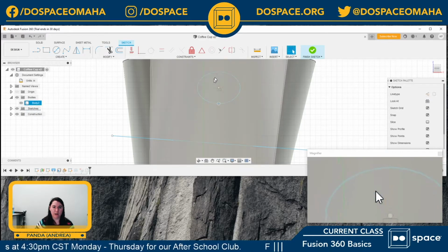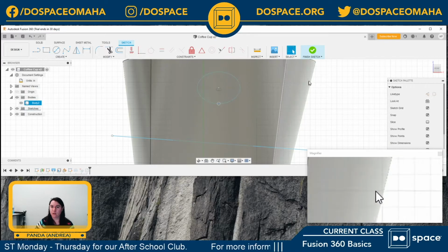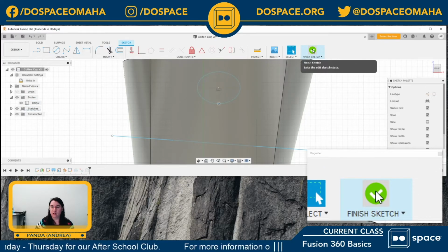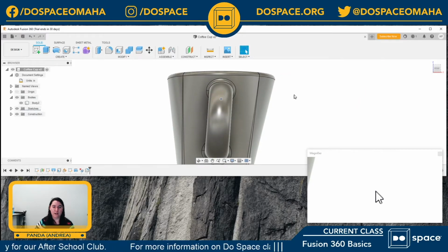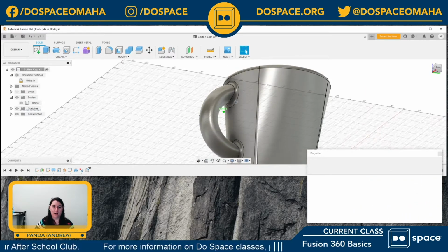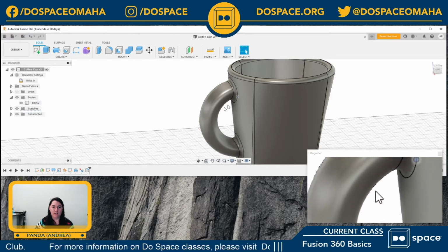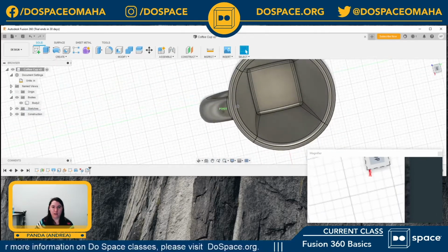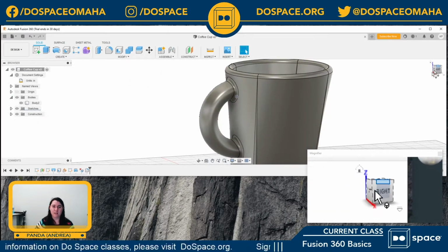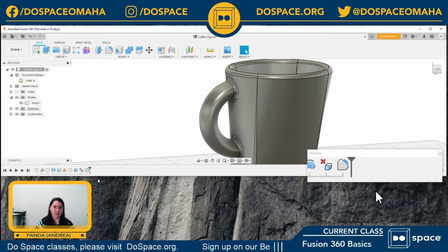So I'll change that right now here. I think that looks pretty good, a little bit fatter than before. And I can check the box to finish sketch. And it goes back and it does all of the steps that happen afterwards too. So I've got a thicker handle now and it is all rounded over. It deleted the little doodad that was sticking out in the middle. Sometimes it'll create errors and you can just go back and fix along the way.